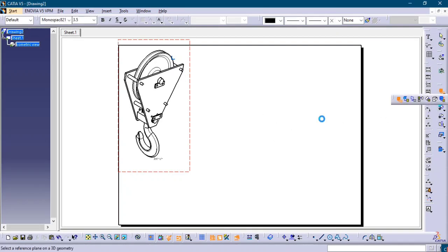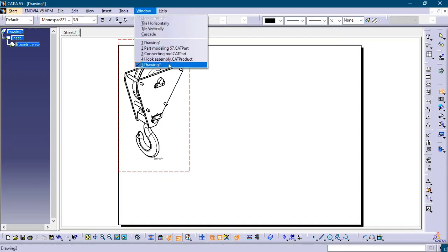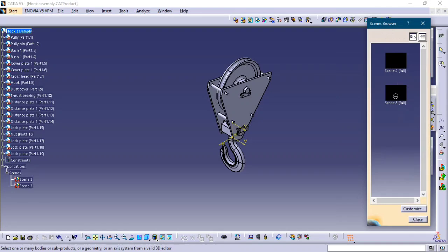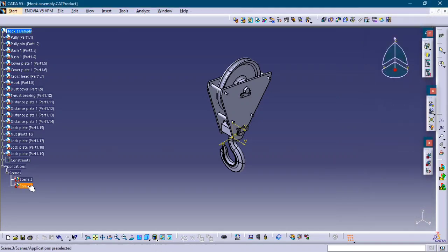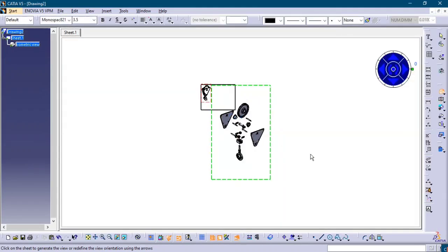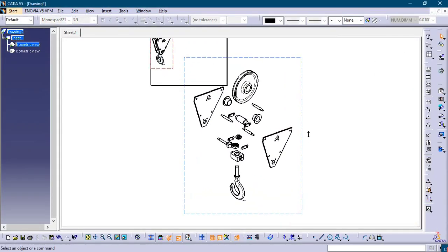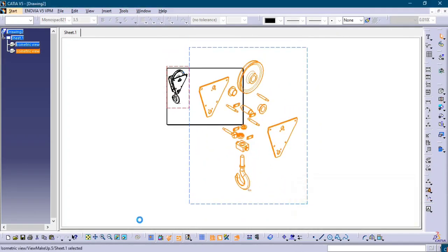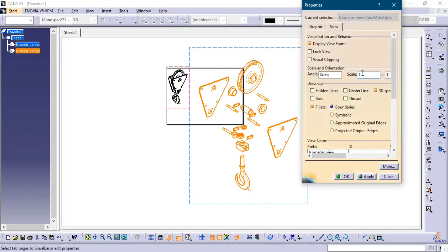In this way, even if there is an update, the parts are not assembled together. So if you want to disassemble the assembled drawing and show that on the sheet, you can follow this process. If you want to change the size, that is a procedure that you learned earlier, and rotating too as well. Now this is okay. I need to give a number to every single part. What I have to do is use the balloon generation option.